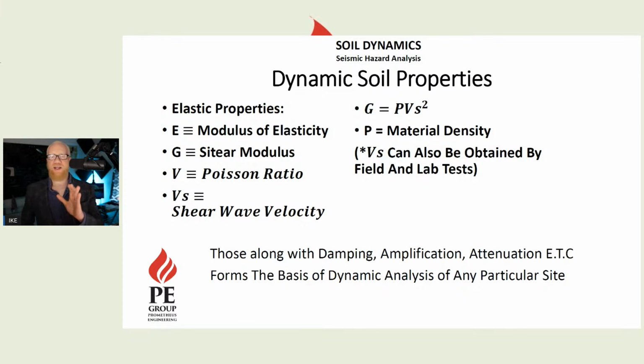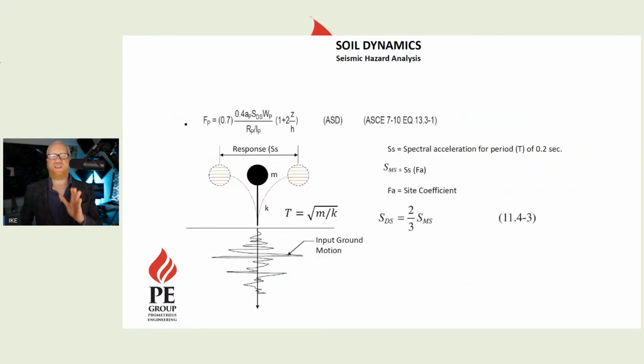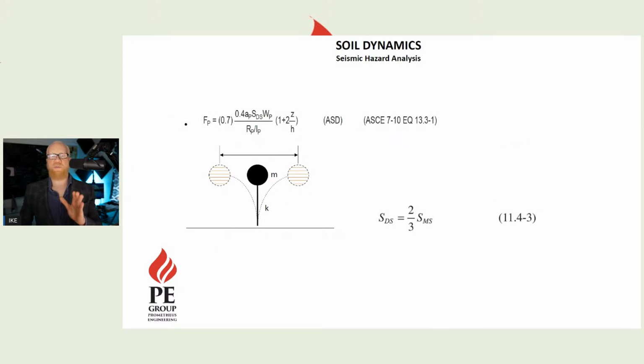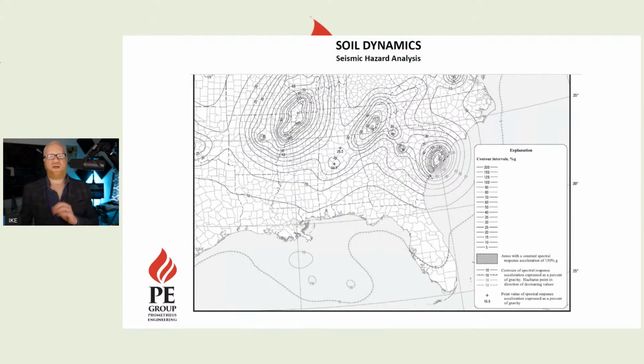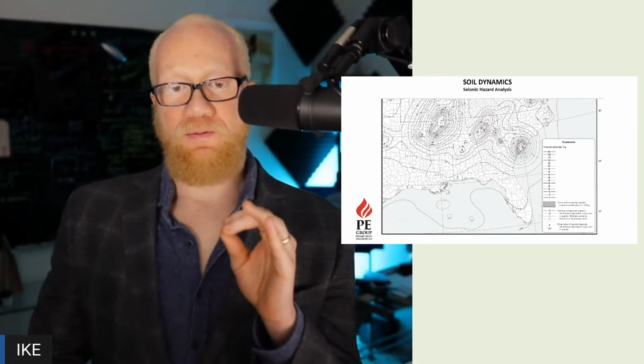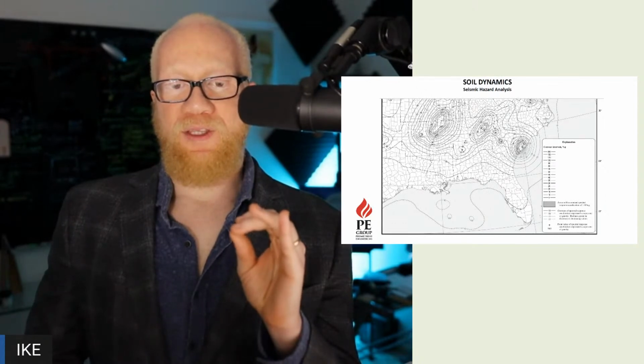And again, as I said, let's go back, and this particular data is mapped. What we're asking ourselves is, how is this map determined? And what does this map show? We say that the map shows a spectral acceleration. But the spectral acceleration is not the acceleration of the floor. It's the acceleration of a single degree of freedom little pendulum that you have on top of the floor that represents your structure, and that you're going to use to model how your structure is going to behave.